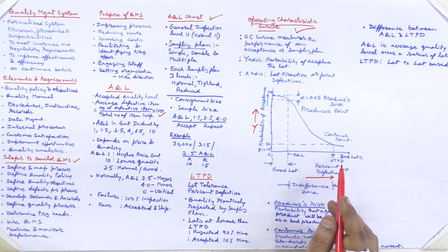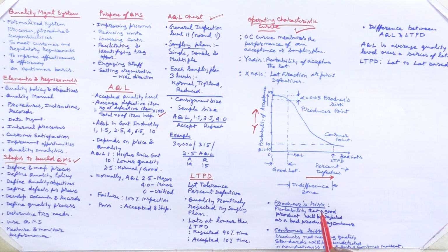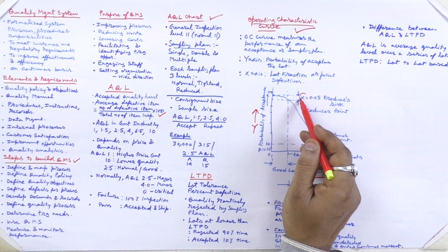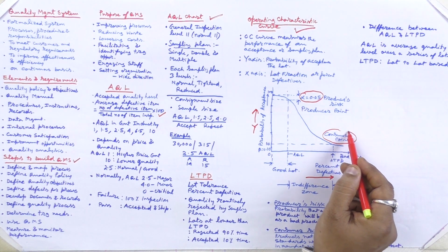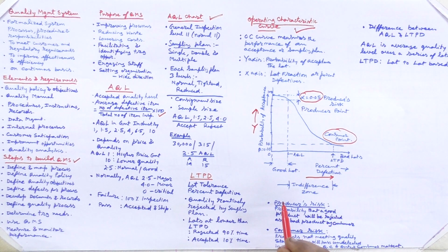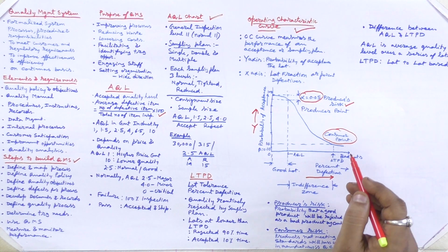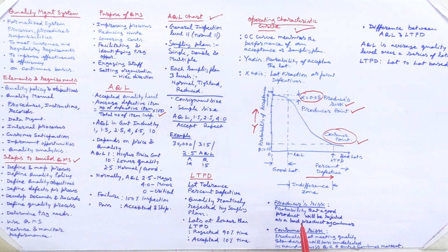Now if we go through this operating characteristics curve, we can see that percentage defects are there at different levels. Now if we see the defects in this fashion, then we can see there are two kinds of zones here. One is called the producer's zone and another is called the customer's zone. Two zones are there in this operating characteristics curve in any kind of sampling plan. Now there are two different risks involved here. Number one, we call it the producer's risk, and second we call it the consumer risk. So the consumer point and the producer point, these two points are there in this curve.